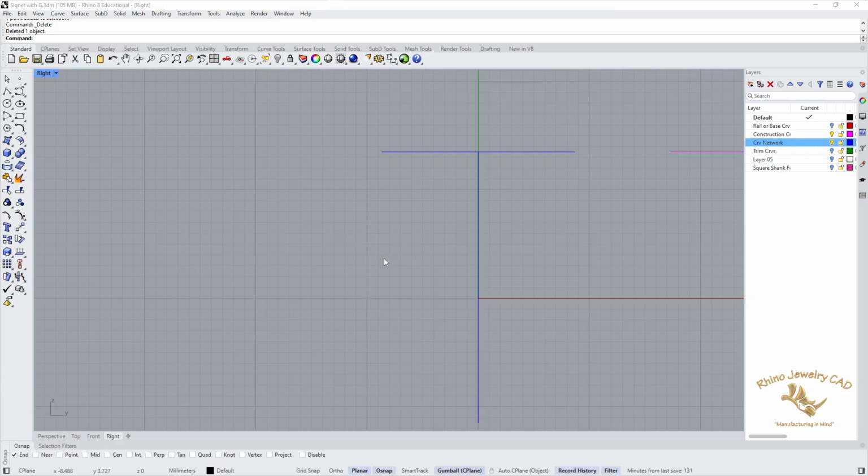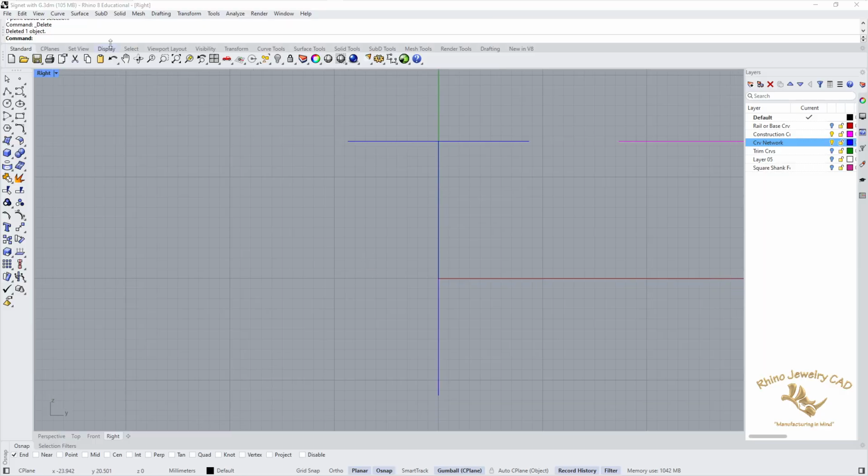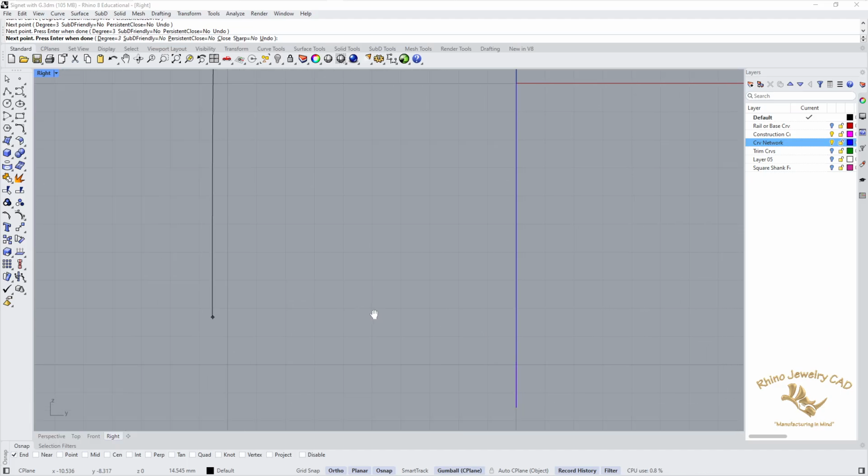Okay, let's go in the right viewport and recreate this curve from, oh, actually, I need quad up here, snap to the quad, right? And then I'm going to turn quad off, leaving endpoint on, and I'll quickly try and recreate this situation down here.